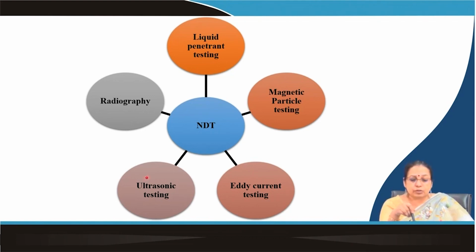Similarly, ultrasonic testing has some limitations on thickness, but it can go up to a certain micrometer of the subsurface region to know the defects present on the surface as well as the subsurface region. Among all these techniques, radiography is the technique with the maximum depth of penetration. This technique is usually applied for the measurement as well as detection of subsurface defects, and also the defects which are present deep inside the component, even at a larger depth or throughout the material. Whatever defects are there can be detected by the radiography technique.